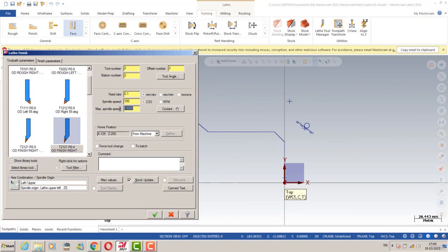Of course, at that point we also need to decide our maximum spindle speed according to my diameter or my tool length. My tool length also depends on the tool diameter, and so that's why we prefer to use the constant cutting speed, not constant spindle speed. We're going to focus on the constant cutting speed.